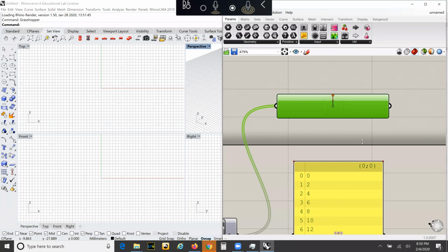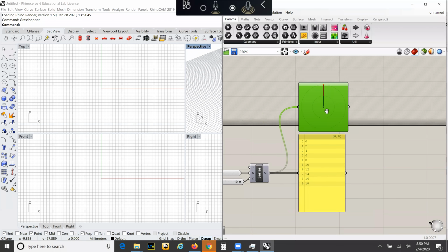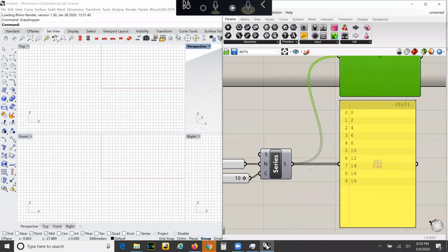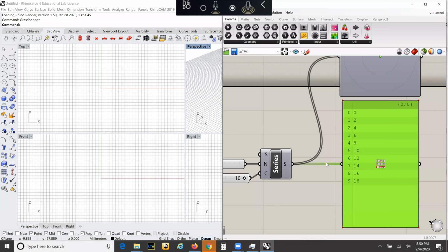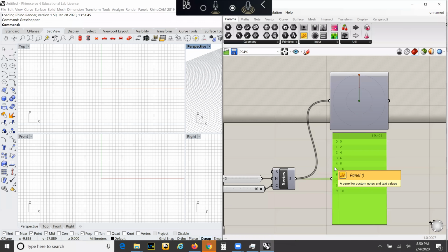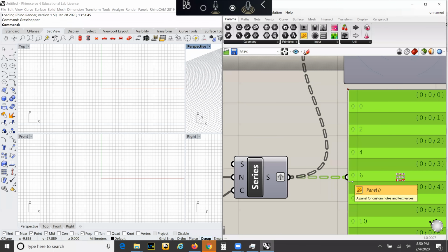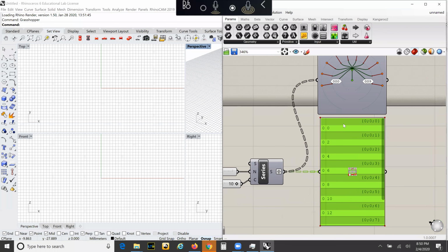And we can see our branch is just one line. Even Grasshopper tells you when it's just 2 lines like this, it means that it's just making one branch, or one stem that's being generated. However, when we switch to graft, we notice that the dash line changes, because now it took the output and made it into all little branches instead of one trunk.